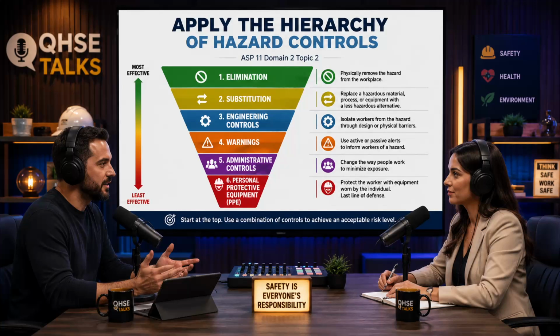Identifying the hazard is knowing the chemical is toxic. Considering the failure mode is understanding exactly how that toxic chemical might escape its containment. That distinction is so important. Which brings us to steps 4, 5, and 6, which seem to be the data gathering phase.